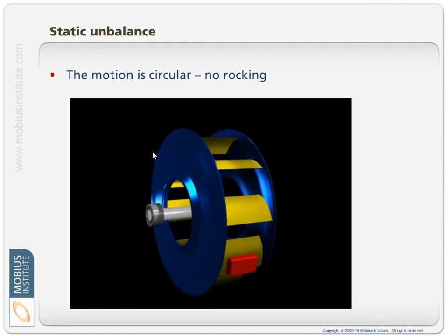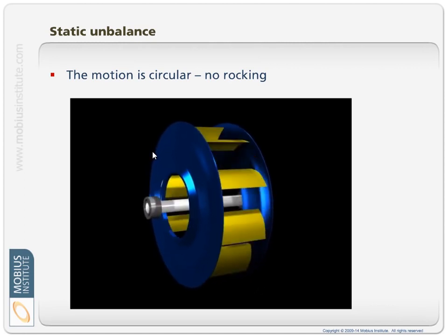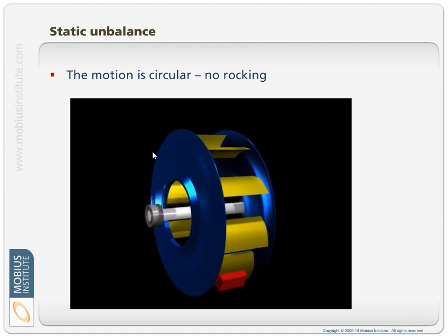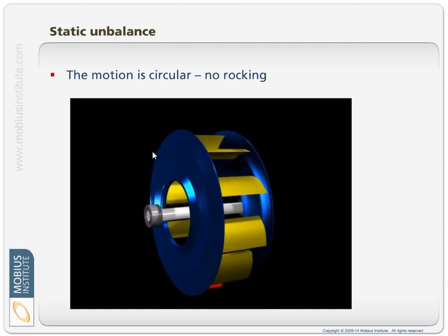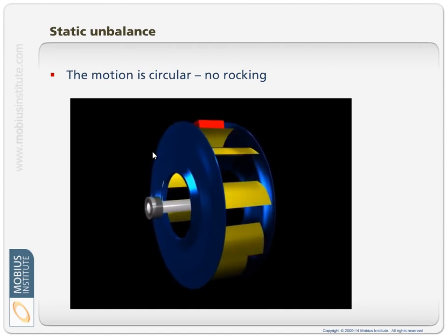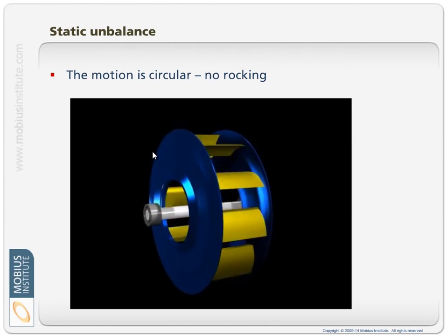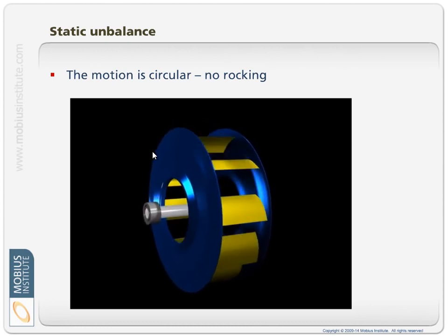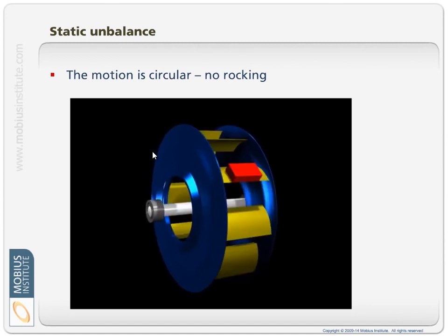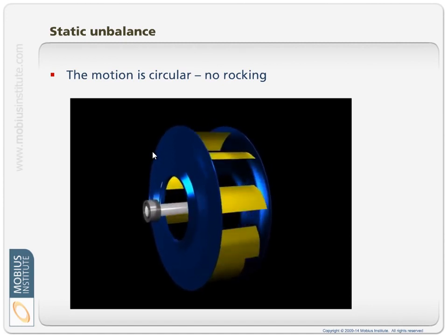90 degrees because it's 90 degrees between vertical and horizontal, and it's moving in a circular motion. But you might think, well, wouldn't it always do that? No. With other fault conditions, misalignment for example, just about all of them, it doesn't move in a circular motion. It's very elliptical. It moves in funny ways you wouldn't expect. That's what phase tells you.